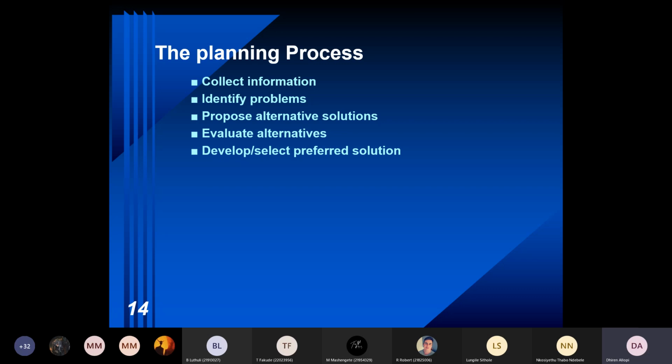You could look at various alternatives. You could consider the signalized intersection in this case. Look at the traffic lights, look at the amount of green time allocated. Perhaps that traffic light did not even allow for right turning. So you need to change the signalized setting to maybe give priority, a green arrow, to right turning vehicles.